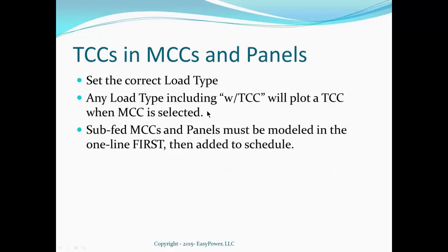So first thing we're going to talk about is the ability to do time current curves, or look at time current curves for devices that are within motor control centers and panels. If you're entering the MCC and panel loads in the schedule format that we give you as an option, you can always model the MCC or the panel as just a normal bus in EasyPower. So the other option is to use the MCCs and panels.